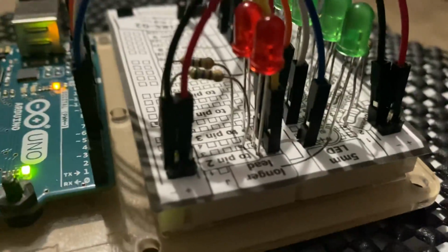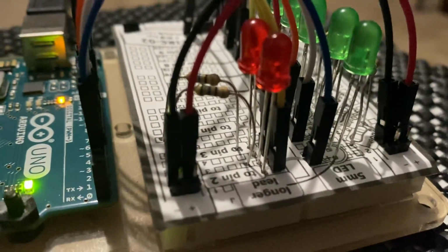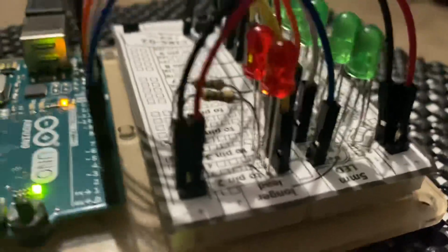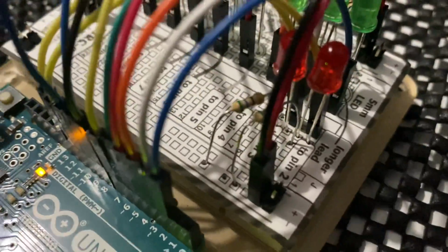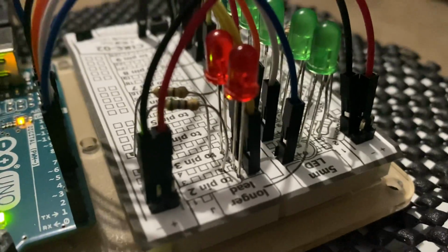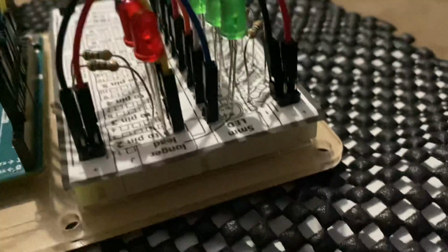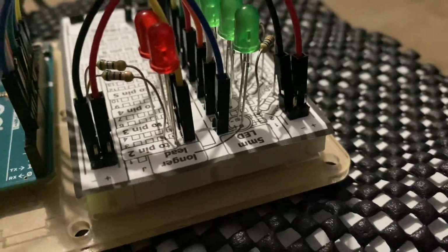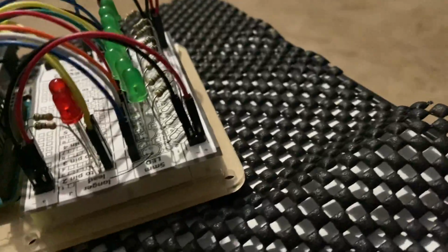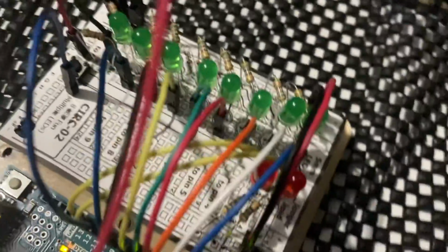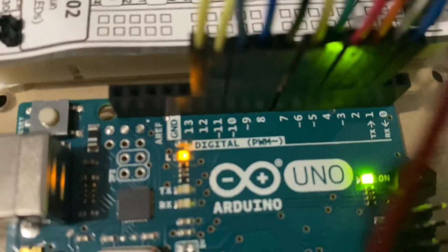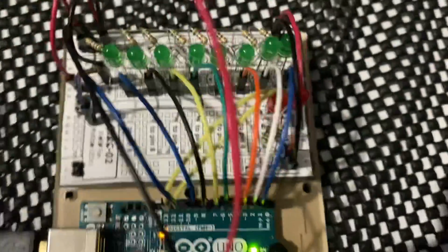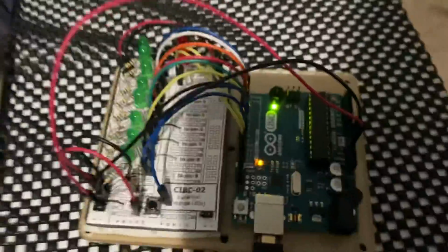We had to connect the 2 red LEDs by their own individual 560 ohm resistors over to the ground on this side, to connect the power, and of course to make sure the LEDs don't burn out. And then right through here, right in the back, we have the positive lead of each red, just like the green, going across over to digital pin number 11 and 12. And that's how we got those to turn on and to communicate with the rest.